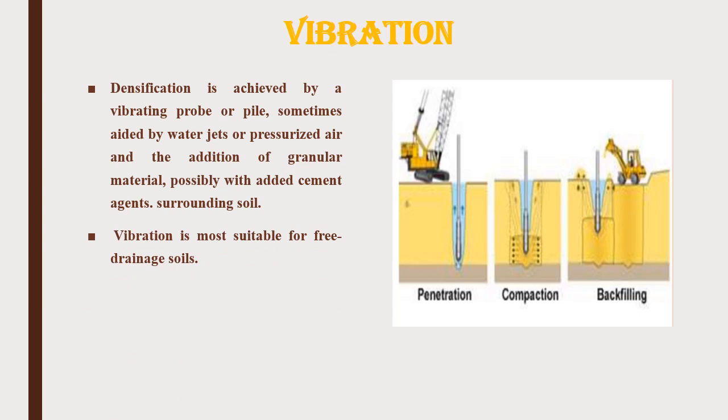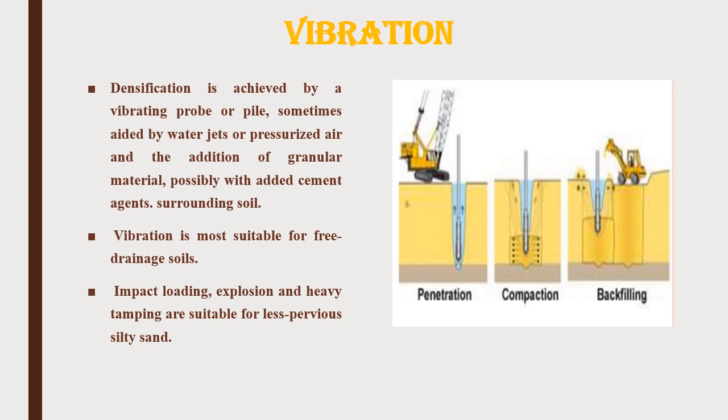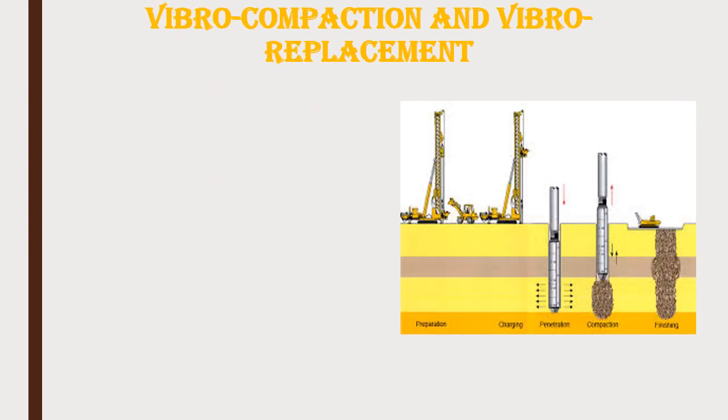Vibration is most suitable for free draining soils. The impact loading, explosion and heavy tamping are suitable for less pervious silty sand. Next is vibro compaction and vibro replacement.